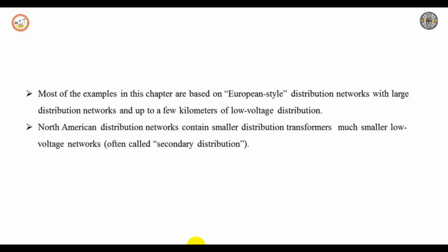The article goes on to suggest that voltage drop can be reduced by measures like implementing a high voltage distribution system, anti-theft measures, and 100% metering so that energy accounting and audit significantly reduce voltage variations or fluctuations. These are some of the articles related to Indian voltage drops and the limits given by Indian standards.